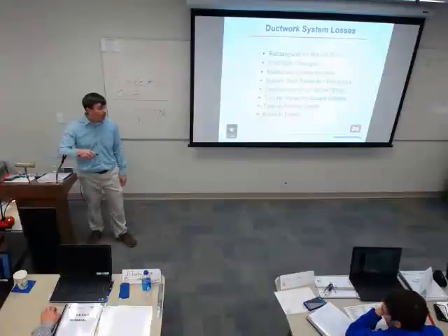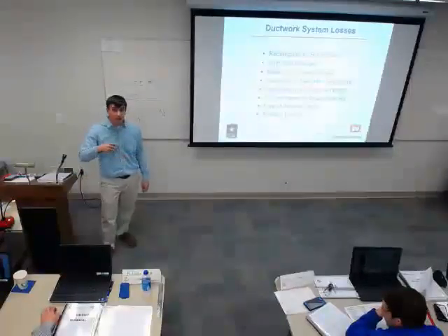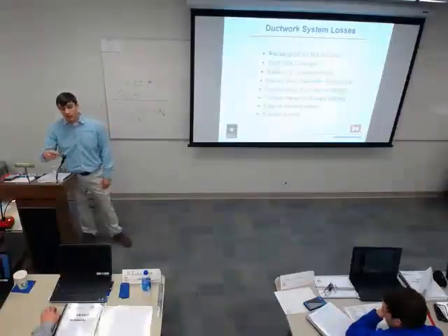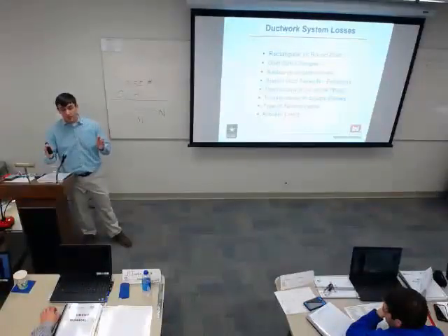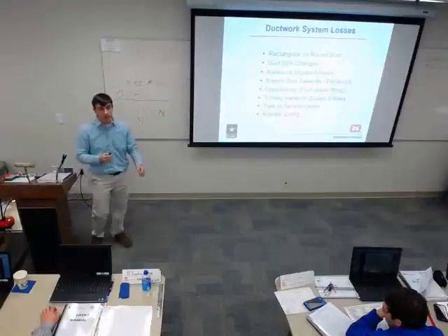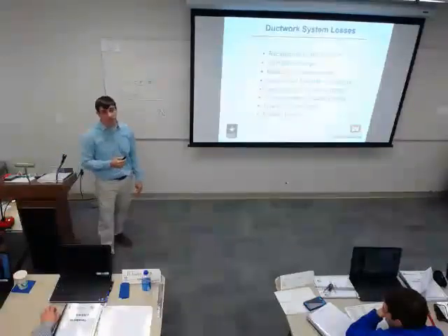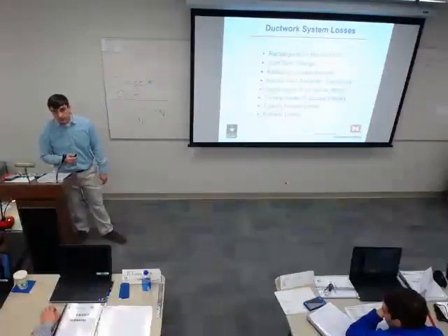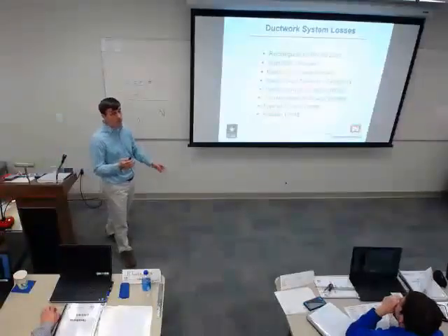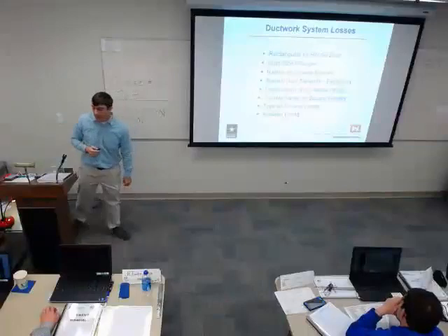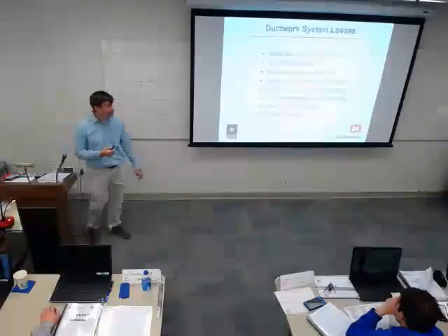Design-build job. I had a contractor submit shop drawings. The designer had approved them, apparently did not look at them, because every single duct was smaller. The contractor said he was wanting to keep the velocity the same. The designer had approved it. He didn't even look. So I said something. Make sure you're paying attention to the duct sizes in shop drawings.